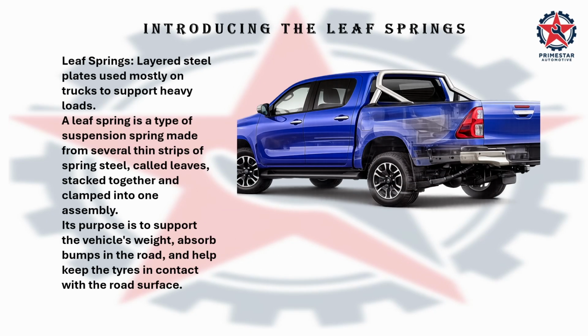Leaf spring suspension. A layered steel plate used mostly on trucks to support heavy loads. A leaf spring is a type of suspension spring made from several thin strips of spring steel, called leaves, stacked together and clamped into one assembly. Its purpose is to support the vehicle's weight, absorb bumps on the roads, and help keep the tires in contact with the road surface.